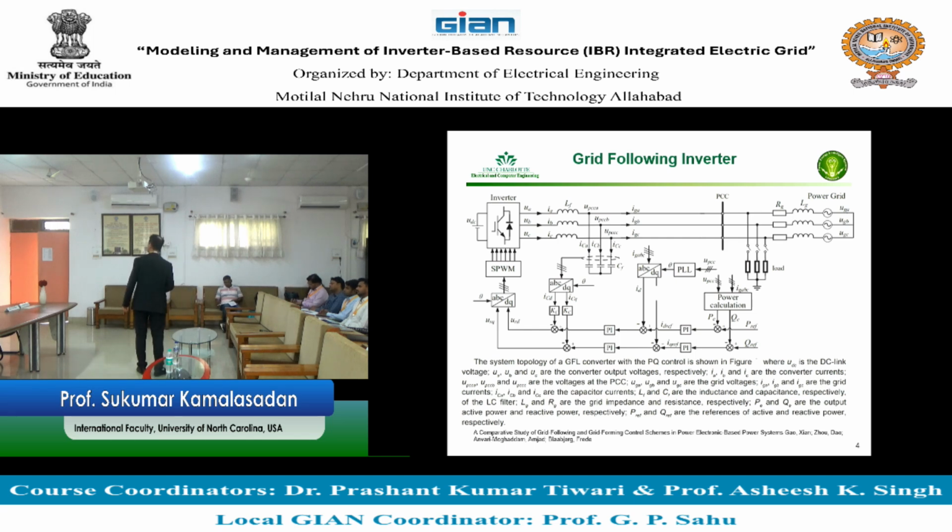So what you do is you take the voltage of the connected part. When it is connected, I know that voltage value, right? Take that voltage and then get the theta out of that voltage. Getting the theta out of that voltage when it is connected is done through a box called PLL. PLL full form is phase lock loop. Okay, and this PLL, how many of you have heard of phase lock loop?